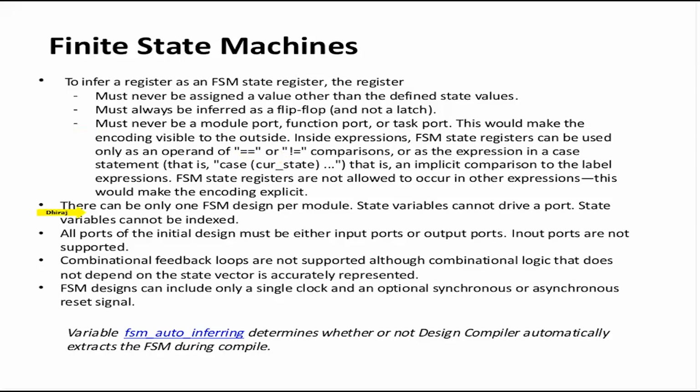There can be only one FSM design per module. If you want multiple FSMs, you need separate modules. Bidirectional ports and outputs are not supported here. Combinational feedback loops are not supported, although combinational logic that does not depend on the state vector is accurately represented.